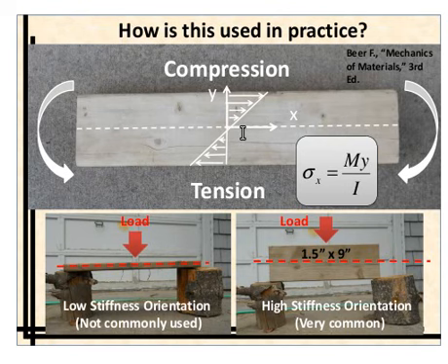So once again, just real quick to hammer the point home, you're going to think this is your 2x4, maybe you apply a load. Now if you were to look at both of these cases, this orientation of your dimensional lumber is going to be less stiff. This is going to tend to deflect more for the same load as this beam here. And it's kind of this taller equals more stiffness point of view. This effectively has a low area moment of inertia, and this has a high area moment of inertia relative to this. So that's kind of the background.